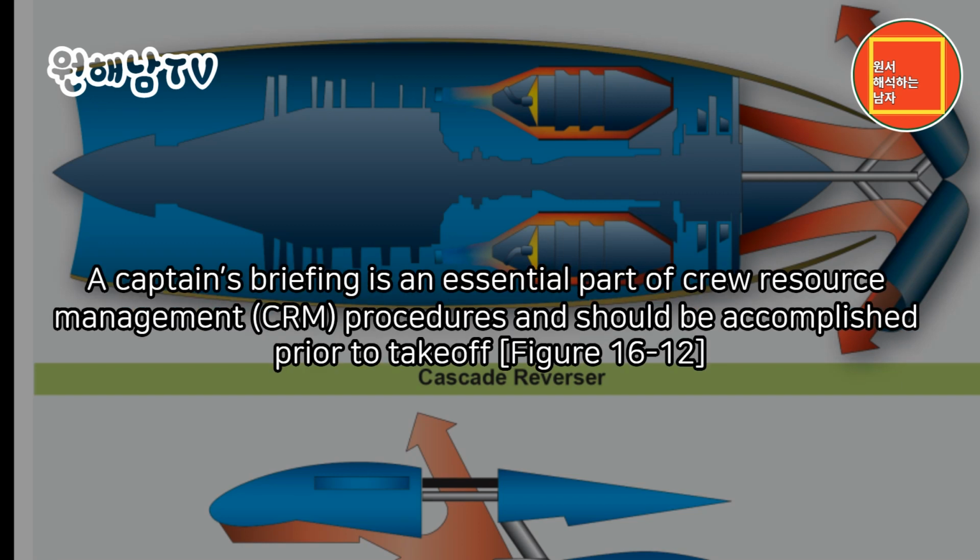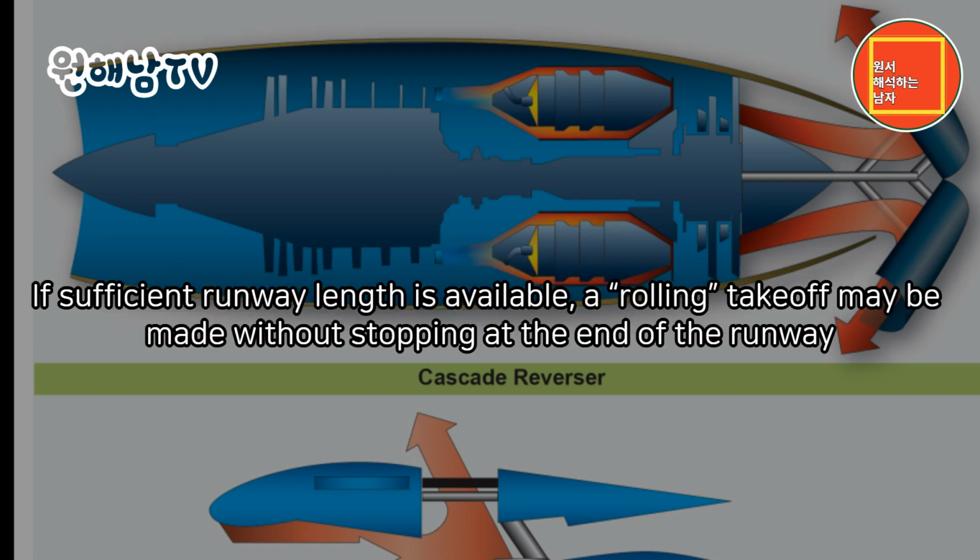A captain's briefing is an essential part of crew resource management (CRM) procedures and should be accomplished prior to takeoff. Figure 16-12. If sufficient runway length is available, a rolling takeoff may be made without stopping at the end of